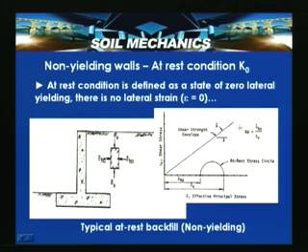So, K naught, which is nothing but sigma h naught by sigma v, is the coefficient of pressure at rest. If this happens to be the shear strength envelope, which is the failure envelope, it indicates that the circle is stable and yet to attain any failure. So, we can say that is a stable equilibrium condition, and that is why we say that at rest condition it actually remains in the elastic equilibrium condition.